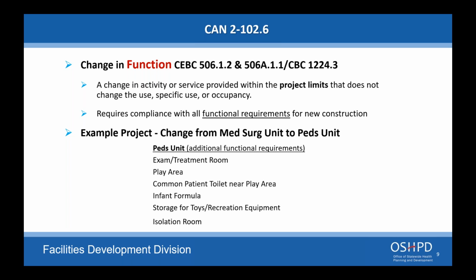Perfect. You need to have 3 feet of access around the equipment. Typically, it's on 3 sides. There are a few requirements where it does go all the way around the equipment. It's 3 feet at the loading. Basically, they want access to the patient on the table as well as accessibility around the table or gantry. But you do not need it behind the gantry between the wall in most cases. I think there are a couple pieces of equipment that do identify 4 sides, but most of them are 3 sides, each side of the table and at the foot of the table.